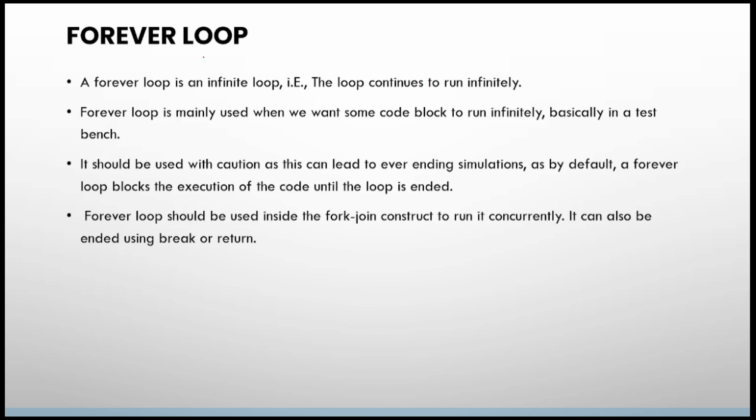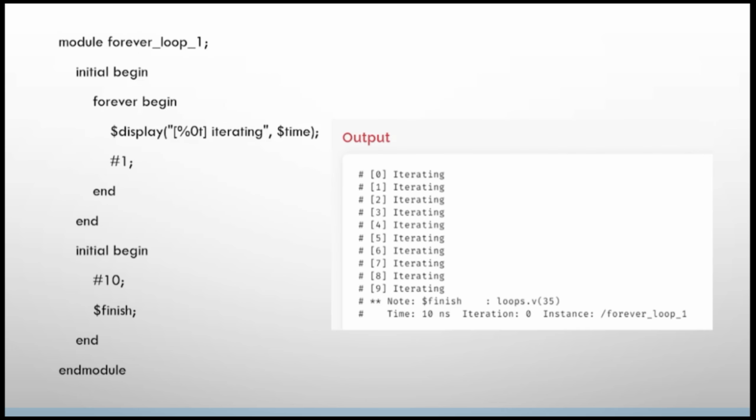Then coming to the forever loop, if you want to execute a particular statement repeatedly, you will go for this forever loop. It will keep running forever until you give a system task like $finish. Until you give $finish, it will run forever.